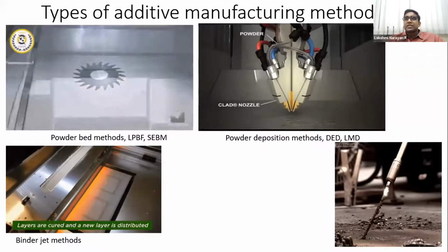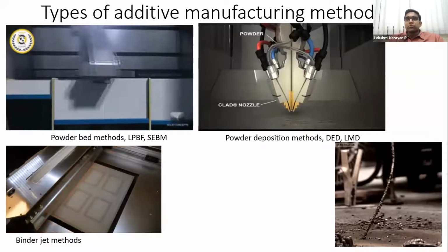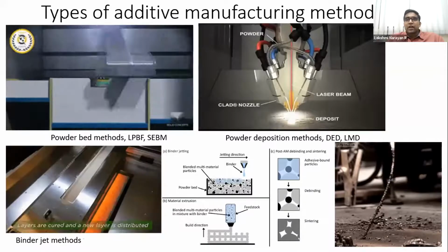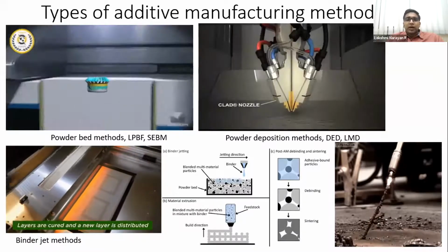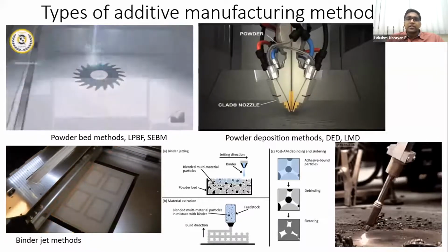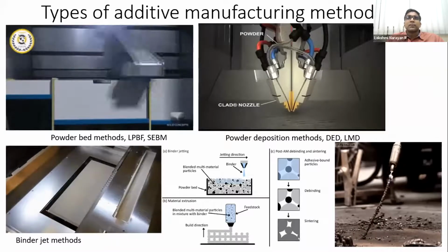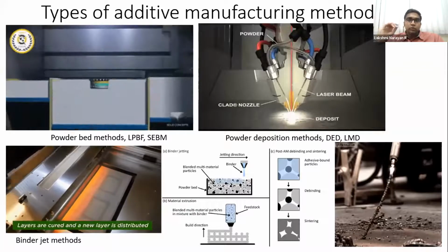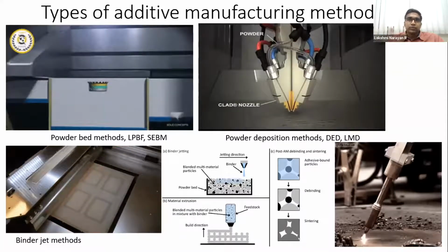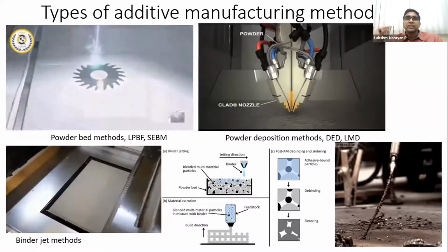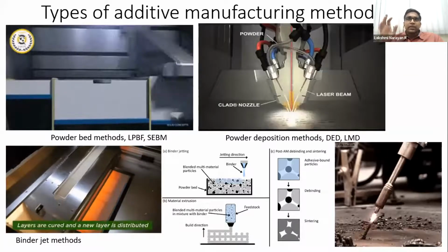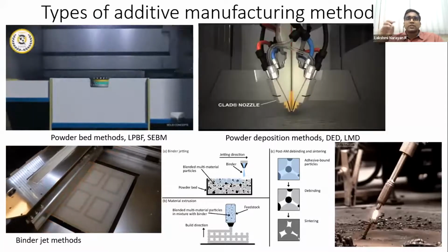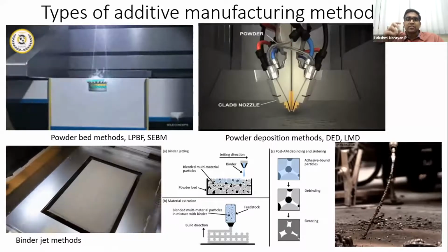But what really happens here is you mix the material powder that you want to print with a polymer that can be cured. So if you have, let's say, even multiple materials, you add the powder and a binder which is then laid over this bed, and then it is cured. So you cure these things by UV light or some kind of energy that will essentially evaporate or dissipate these polymer particles, or the binder particles that are attached,